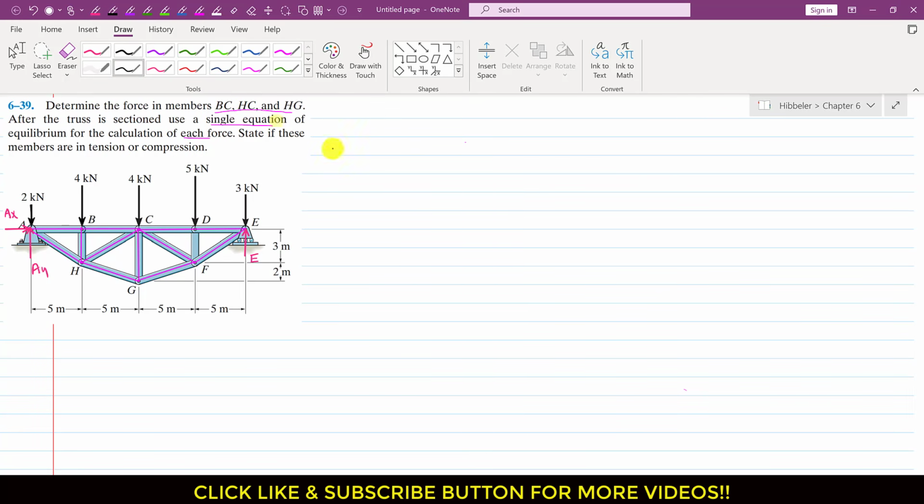Now if I apply the summation of moments about point E equals 0, we will be able to find the reaction at point A. But before applying this equation, if I apply the summation of forces along X equals 0, as we can see all the external forces are acting in the Y direction, that is, the vertical direction, right? So the summation of forces along X gives us AX equal to 0, since only the AX force is acting in the X direction. If this is my positive X and this is my positive Y, then AX is equal to 0. So this means that at A there is no horizontal reaction, right?